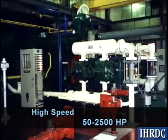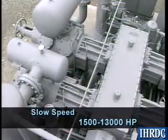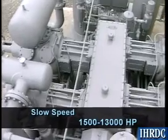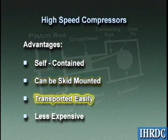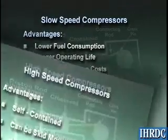High-speed compressors are built in sizes ranging from 50 to 2500 horsepower, and slow-speed compressors are usually available from 1500 to 13,000 horsepower. The advantages of high-speed compressors are that they are self-contained, can be skid-mounted and transported easily, and are less expensive.